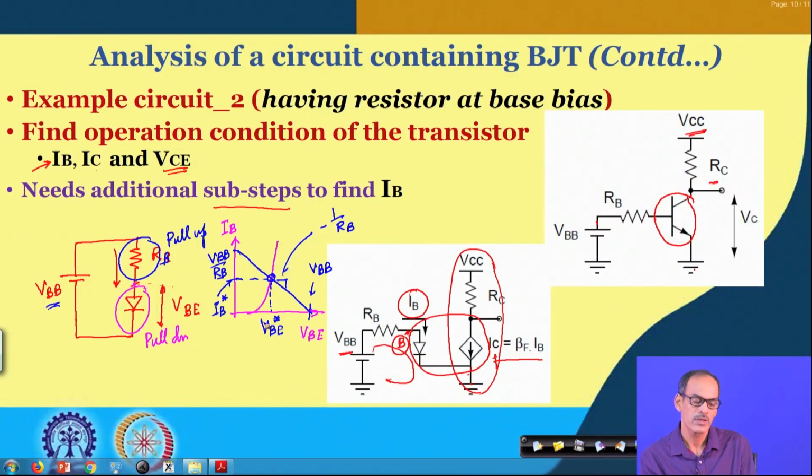Okay, that is the graphical procedure, but what may be the actual method we should follow to get the numerical value, namely what may be the equation? Well, either you can go through iteration. If you know this characteristic and the load line, then you can start from this point, following the iterative procedure we have discussed for diode circuits. Or a more practical method is, instead of considering the detailed diode characteristic, we can approximate it as piecewise linear. In this piecewise linear model, for the diode we said this is the cut in voltage, whereas for this case we call it VBE on.